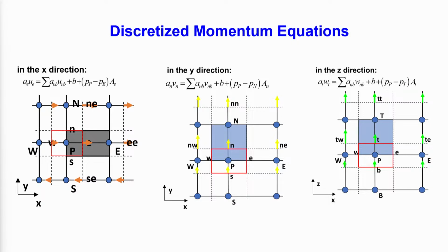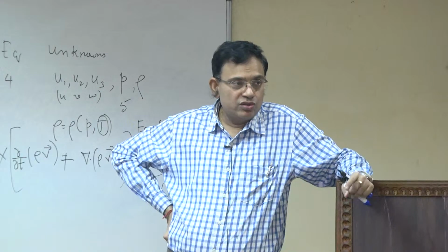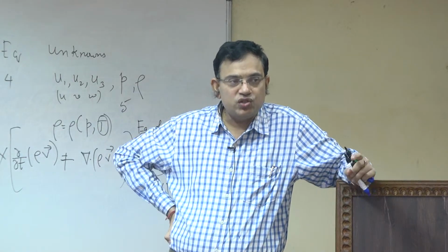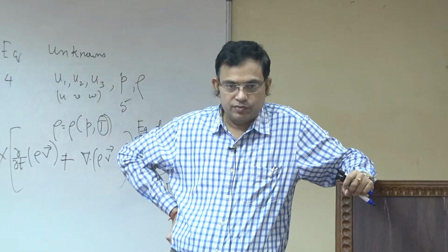So, in that way, you will get it in the x direction, y direction and z direction, it is staggered or shifted, and this staggered means it is staggered with respect to velocity calculation. Okay. So, with respect to velocity calculation in the momentum equation, these are staggered. So, your grid points are now the small letters and neighbors are also small letters, and that is how a change in the name has to be given, like you need a grid point which is the right neighbor, but you have already exhausted the nomenclature small e. So, two small e's like that. Okay. And if you are writing a code, you have to keep in mind that your indices, those i and j, for main and staggered you have to be very careful.